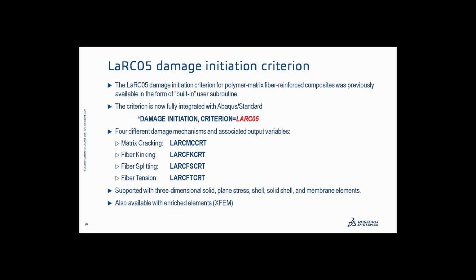A couple of enhancements related to materials, and there's really a whole bunch this release. I'm just going to pick two right here. First is the introduction of a new damage initiation criterion called LaRC05. This is for polymer matrix composites, fiber reinforced composites. It was available for a couple of years as a subroutine, now fully integrated into Abaqus Standard.